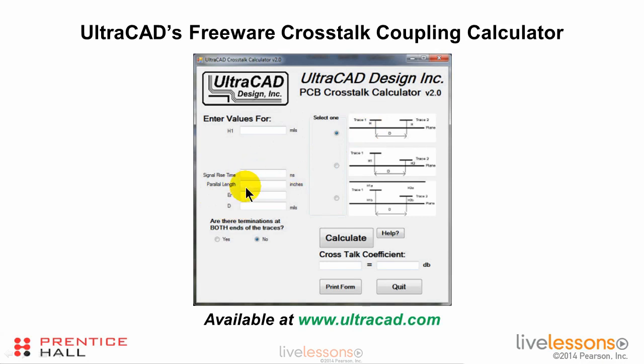You specify the rise time, you specify the parallel length, you specify the relative dielectric coefficient, and you specify the center line spacing, and whether or not there are terminations at both ends of the trace, and then calculate the crosstalk coefficient, which is expressed as a fraction and also in decibels. And we have 3 different types of configurations that can be used for estimating the crosstalk coefficient.